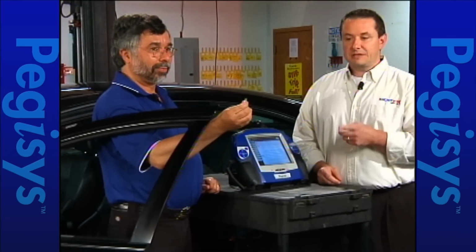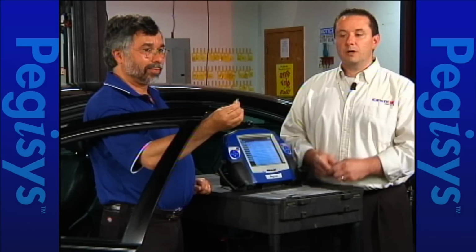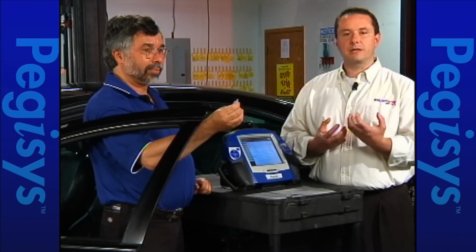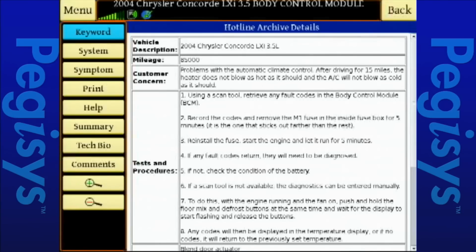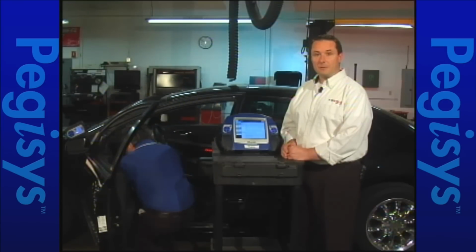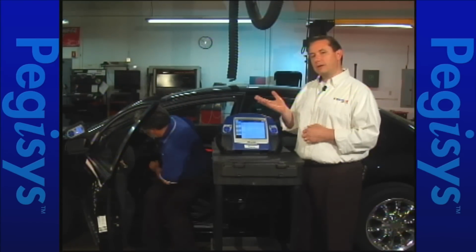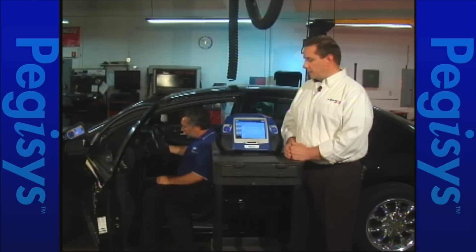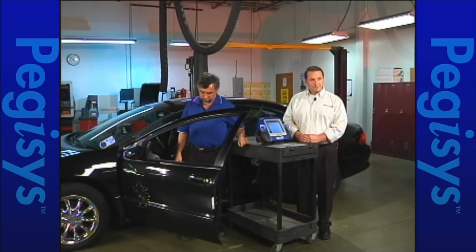The reason that we're doing this is that fuse is a battery supply power for the body control module. What we're going to be doing here is forcing that body control module to do a recalibration on the climate control system once we reinstall the fuse. Okay, we've had the fuse out for 5 minutes. Now we're going to go ahead and reinstall the fuse, and then start the engine up. And remember, what's going to happen here is the body computer is going to recalibrate the climate control system. We're going to let this idle for 5 minutes.